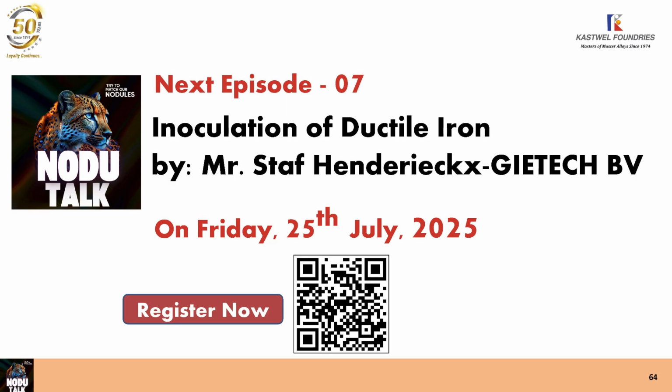The third thing is the oxygen. You know where the oxygen is coming from. The oxygen is not coming from the metal at the location of the mold, because magnesium, rare earths, and calcium have removed it continuously. But then you pour. If you pour from 500 millimeters above the mold, you will already absorb a lot of oxygen again. So keep a low height between the ladle and the mold.